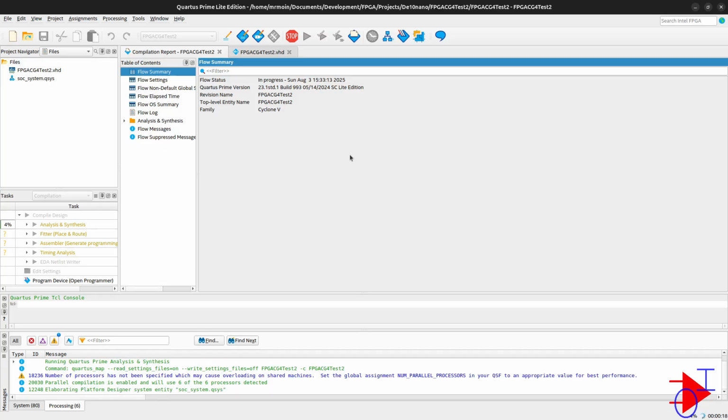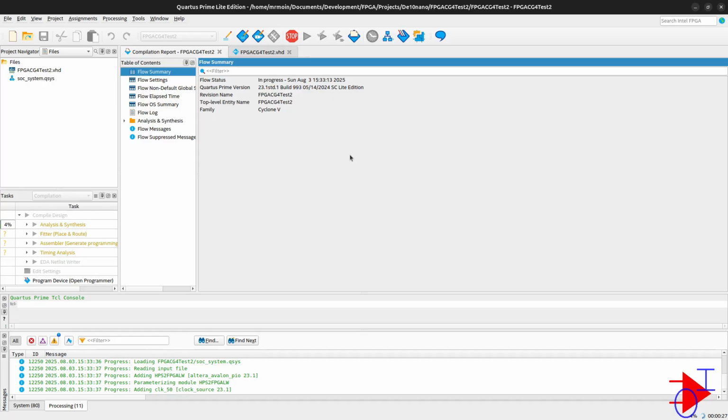execute something called TCL scripts. Basically, the QSys project that we create has its own internal connections. The TCL scripts allow the project to make those connections to the original project or the master project. So let's allow it to complete first. Let's see if it does that. Maybe I have to compile it twice to complete those connections. Let's see where it goes.